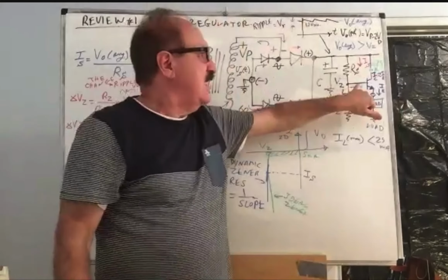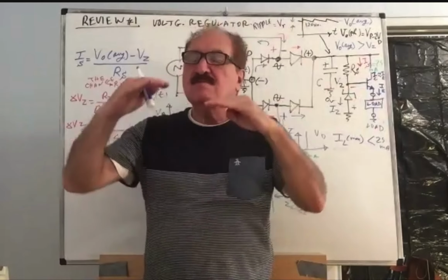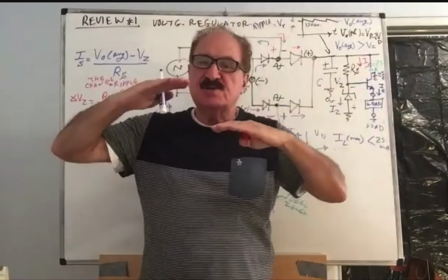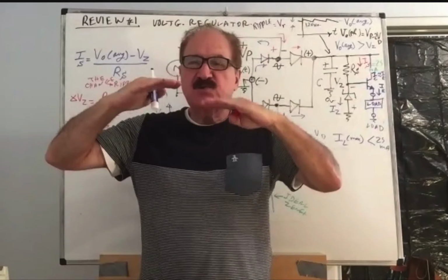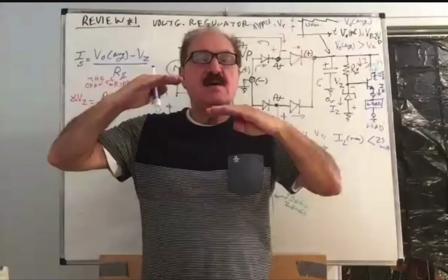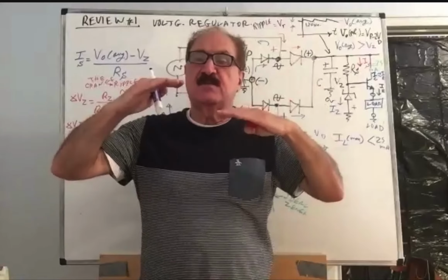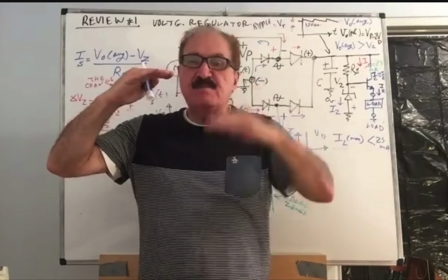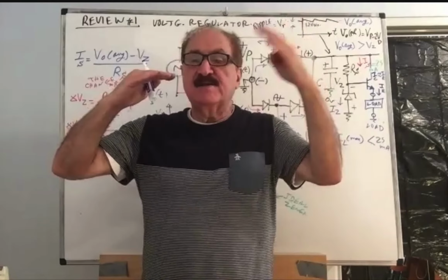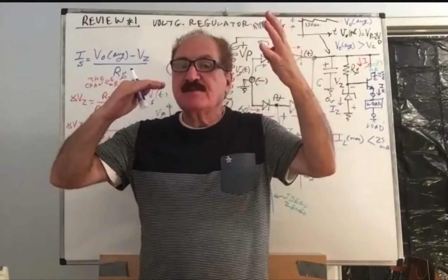We know that transistors give a constant VBE. It is not really constant, but if the VBE is changed by 25 millivolts only, the current in the collector will triple. So if VBE changes by 50 millivolts, the collector current can change by 9 times.